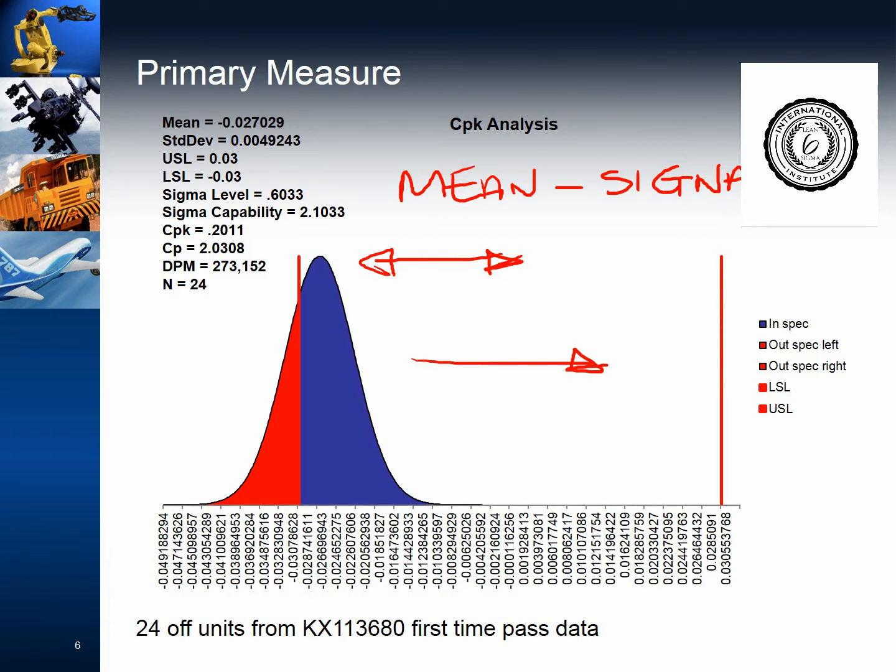If what you're trying to do, on the other hand, is affect the noise, if you've got a capability problem that looks like this, for example, and the defects are sticking out both sides, so it isn't about moving the signal. That is about squeezing the noise. If you are trying to squeeze the noise, that's going to take 3 months. This is going to take 3 days. Maybe 3 minutes if it's a dial on a machine. So there are the diagrams telling you, what's my problem? How difficult is it to fix? What have I got to do next? And this is what these diagrams are about.